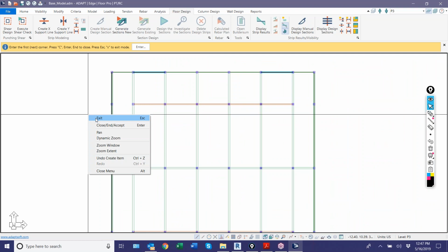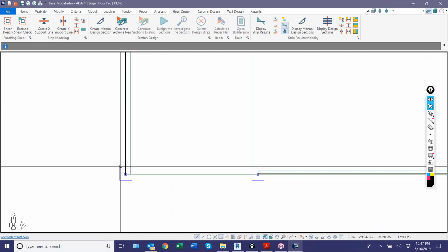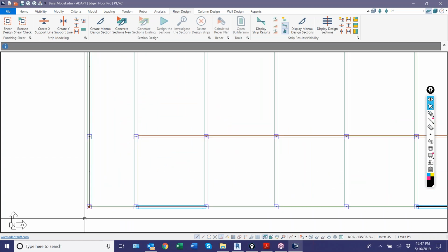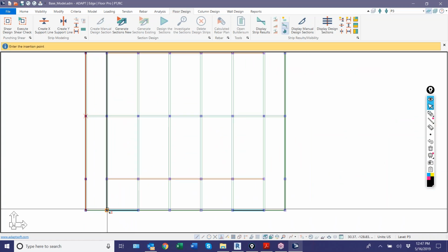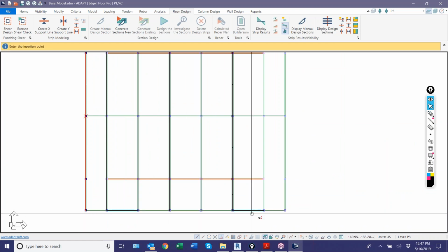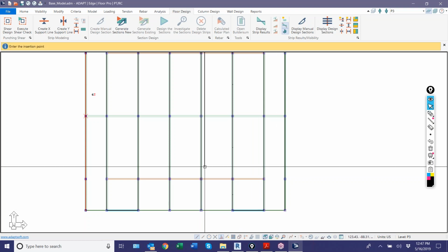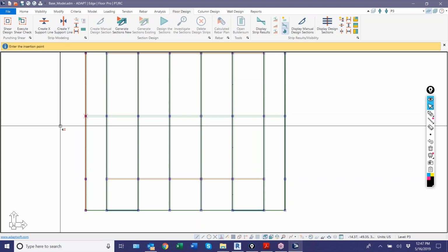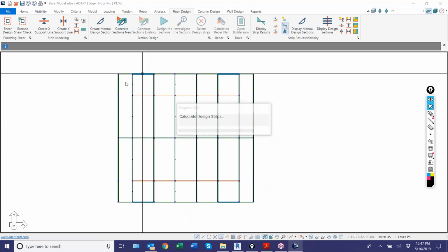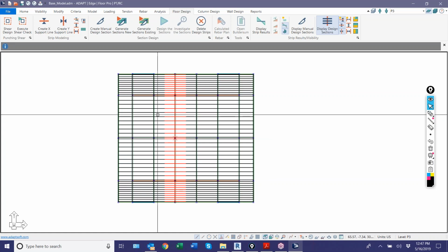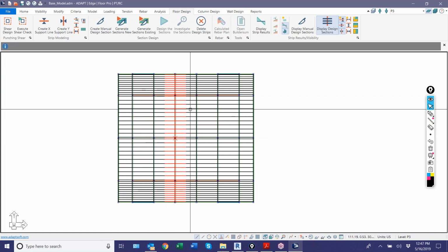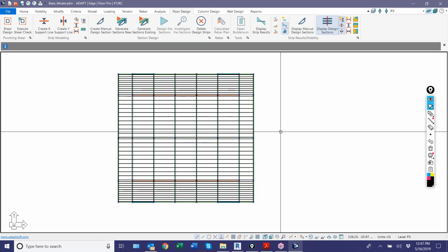Okay. In this example, which is often the case with these types of slabs and one-way slabs and beams, I really only have to model one, and then I'll just copy paste it over multiple times. If the spacing is equal in the X direction per bay, you could also use modify copy paste multiple times. So those are the support lines for this direction. If we generate them, you can see they're all set like so. If you notice, these are full tributary strips.